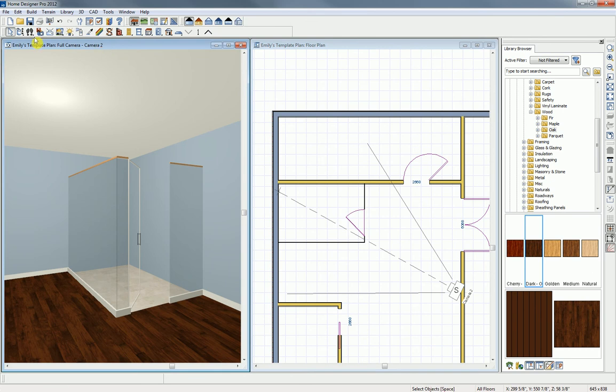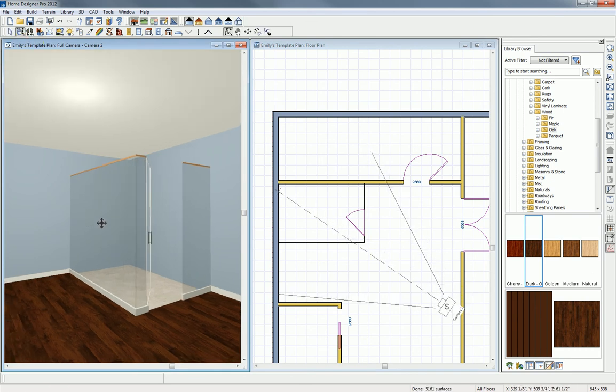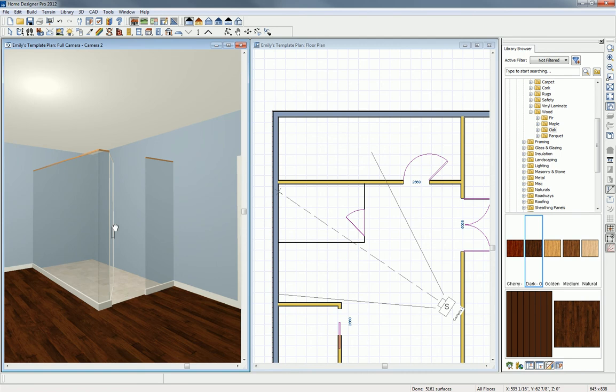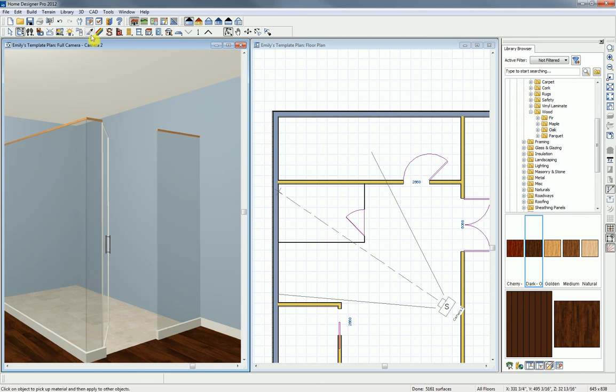So let's address some materials right now. I'm going to zoom around here. And holding down my scroll wheel, I'm just panning over. So we have some different materials going on. So we have a material eyedropper. With the material eyedropper, you can single click on the glass and you can see that it is a paint roller. The roller means it's going to blend the material with the texture. So down here, we can uncheck blend color with material, so it just changes that material to glass instead of blending it with whatever is assigned.